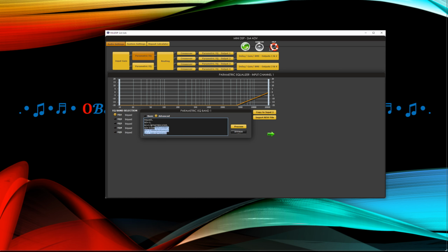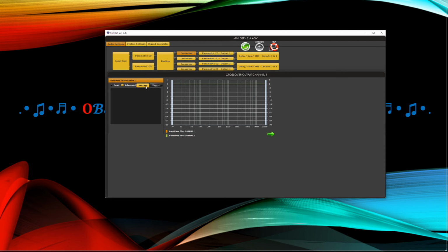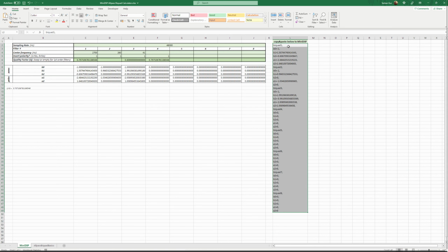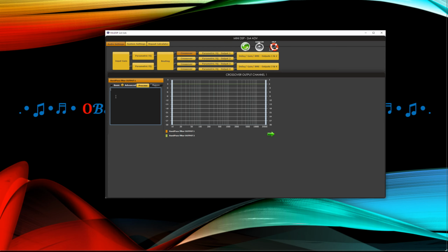Well, you have to enter here one by one, unfortunately. It doesn't accept all 5 at once, but there is a limit of 5 biquads here, and they can all start with biquad 1. It doesn't matter what you see after processing. This was empty, that's why. Now this is limited to 5, which will not be accepted. Let me do it one more time. Copy and paste here and process. And the processing goes without any problems.